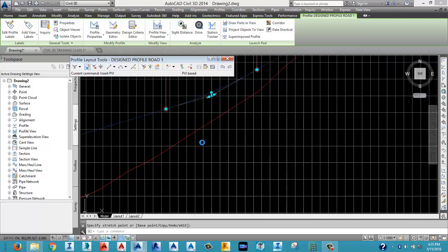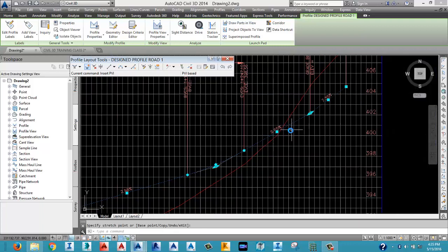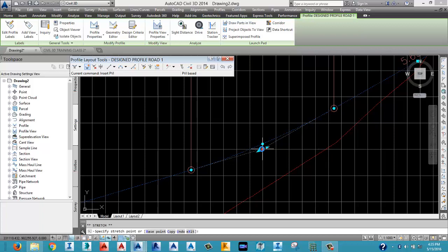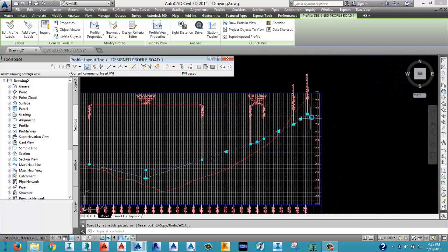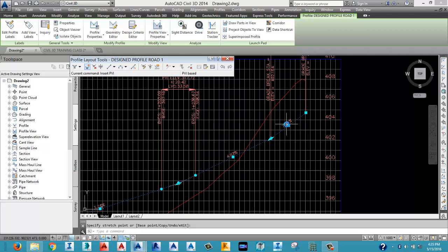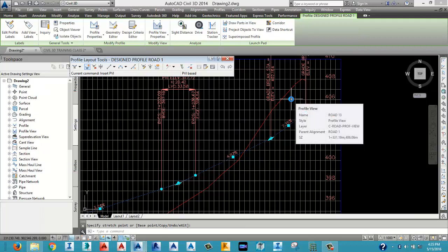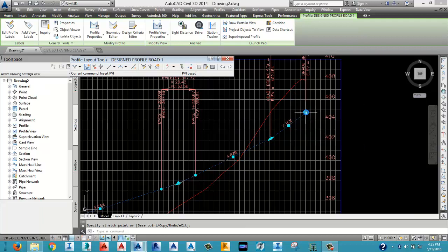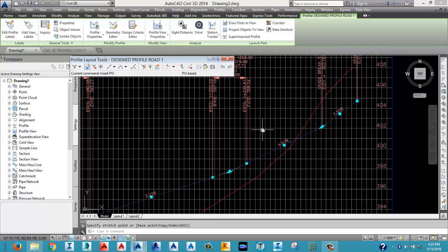So those cuts, is it the grader that did the cutting? No. The grader doesn't do cutting. What's your bulldozer meant for? Your bulldozer is there, your excavator is there. The excavator is there to do so many of your cuttings. Your bulldozer clears anything that is obstructing. The bulldozer is the one that has a big blade and moves like that. The grader is just meant for you to spread. That one that's under is the grader. It spreads, it scrapes, then enables it to compact.